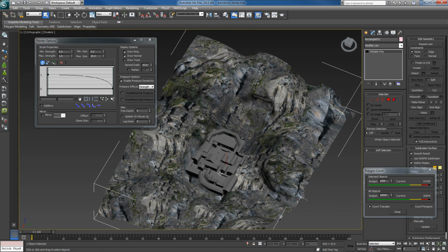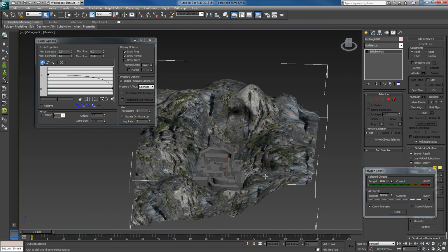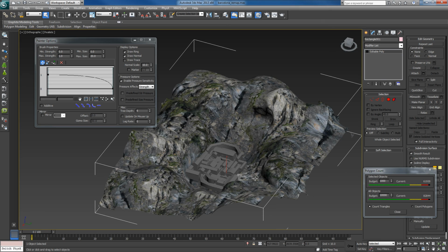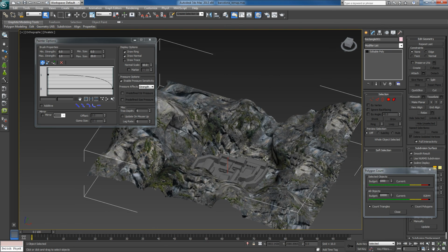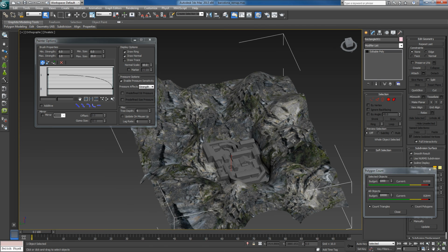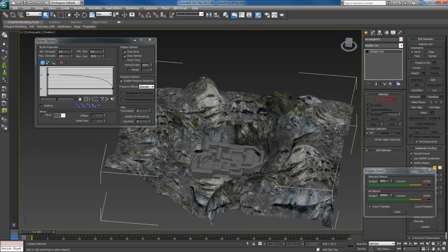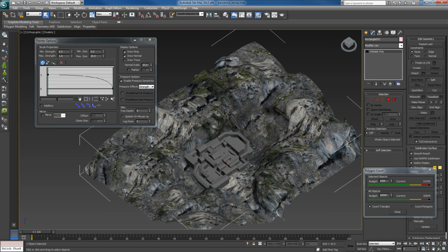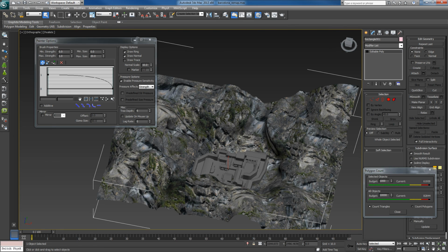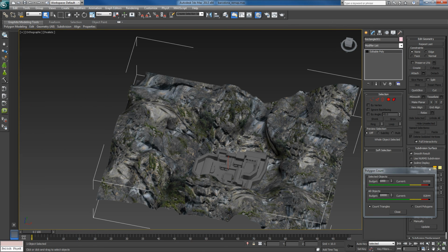So first of all, we need to take into consideration that we probably need to segment this map later on into pie shapes, to wedge the culling effect that the engine does as to detail. For example, if this was a 64K model in front of us, we can turn our back, and if it's not seen, then it's not rendered. And with a mountain, if we see one little freckle of vertex, it renders the whole thing in full. So if we cut these down into segments as units, then if we don't see it, it gets culled, and that adds to the performance envelope.